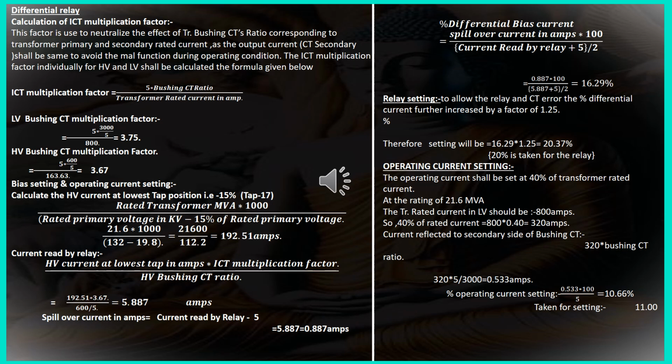So your duty is to give the terminal to the contact where it is instructed. But you should know what it is. For this we are discussing, but in the relay we will do nothing except the CT polarity connection.